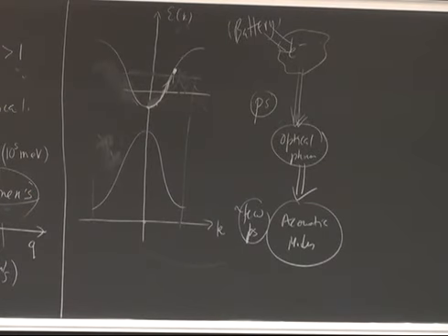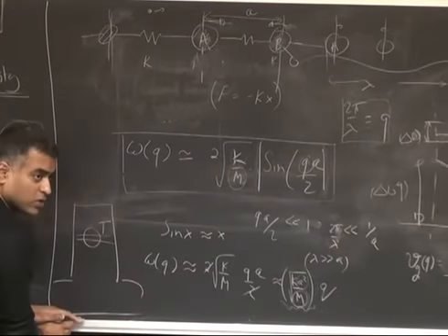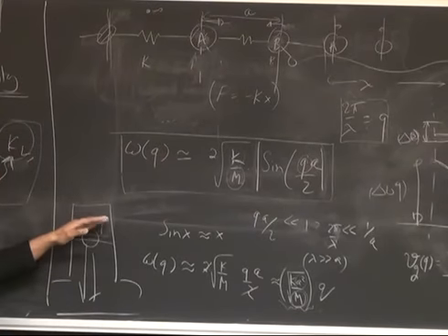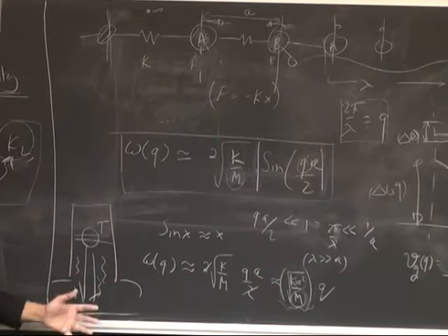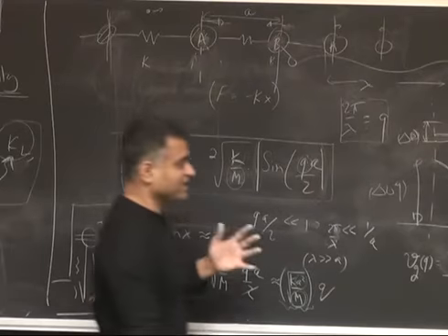And then the acoustic modes' job is basically to carry the heat away, because the place where you generated it inside your laser bar, let's say, is very hot, and out here is much colder, so the heat current starts flowing. And the acoustic modes are carrying the heat current. The sound waves are what is really carrying it out. Okay. Does that make sense? That's the microscopic picture of all the details.